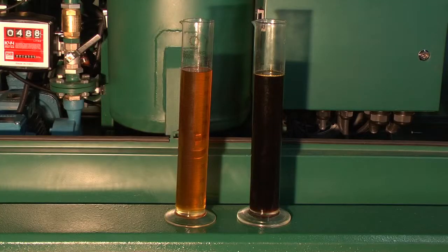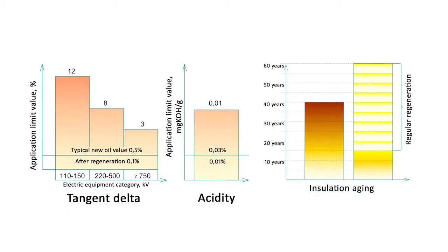This technology surpasses the existing systems in both quality of oil treatment and ease of servicing. The ability to treat the oil directly in the transformer is an additional advantage. Reusing the same sorbent many times saves labor costs related to sorbent replacement and eliminates storage and disposal costs. The efficient sorbent reactivation technology keeps the electric energy costs of reactivation very low.